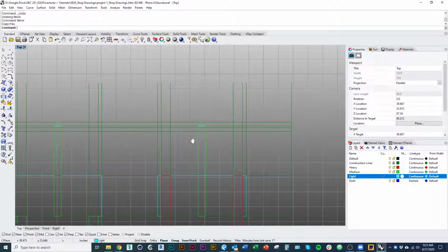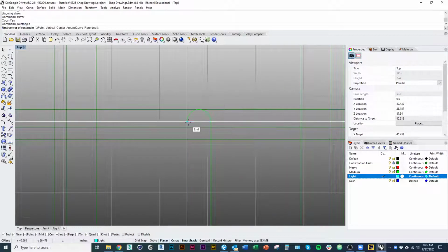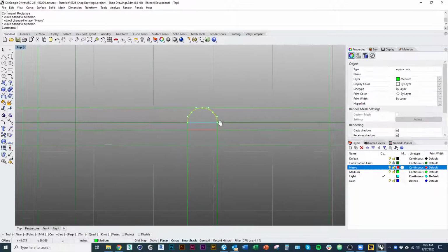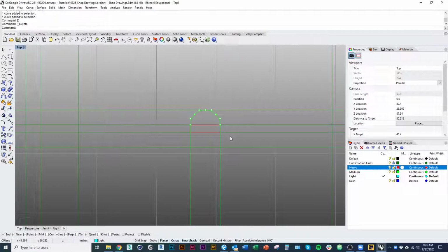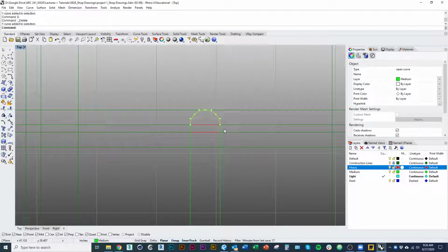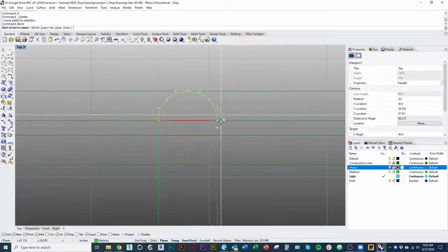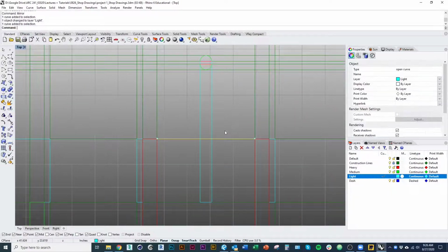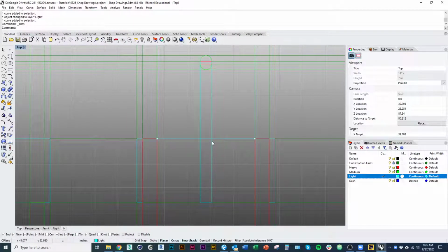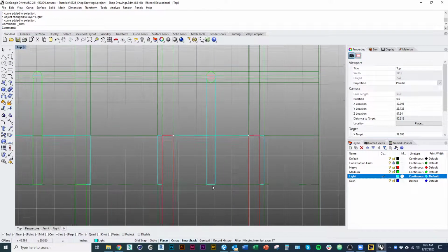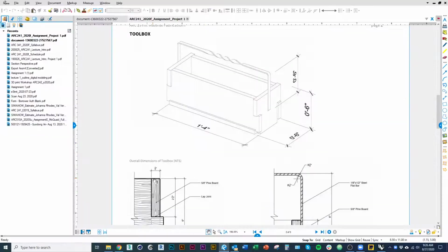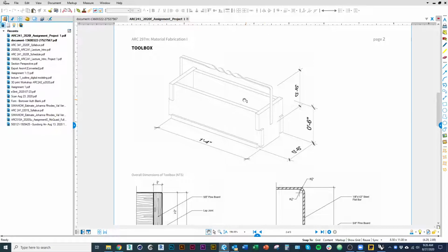Okay, and then the only other thing to show would be we'd be seeing the middle of the handle, and we'd be seeing kind of mirror this as well. And then the back of the handle, we'd actually make that a lighter line weight. And I could even, so right here, for example, if I wanted to show this, and again, that would actually be behind, that's behind the back of the box. So right here, I'm looking this direction. So the side of that handle is beyond the back face of the box.